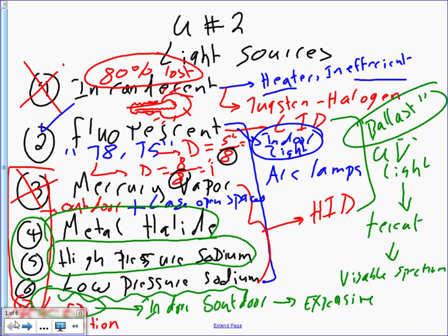That's a drawback of mercury, metal halide, and high pressure sodium. First they need 5 minutes to come up to speed, meaning go to full brightness, right? And then when you turn them off and on again, they will take 15 minutes to cool down and come up to speed. Now, can I use them as an emergency light then? No. You lose the power, you try to ignite them again, they can't be used. So that's a drawback. That's why fluorescent is taking over. High bay fluorescent, we're going to talk about this one, guys, in LEDs.